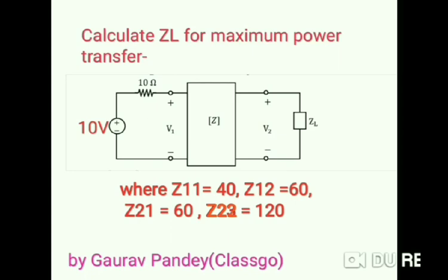So in this particular numerical, hereby we are having a DC source whose frequency is, as you know, 0. So it means the impact of inductance or capacitance will certainly get nullified, because in the case of inductance we know that it is j omega L and frequency is 0, so XL will behave as a short circuit and likewise capacitor will behave as the open circuit. So here we can say that ZL is basically RL. It is a load resistance.